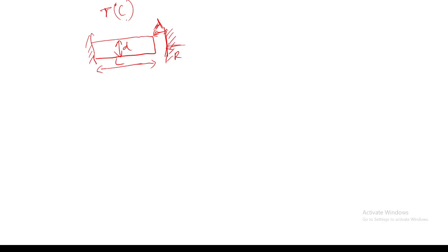Clear, sir. I am continuously increasing the temperature, and the thermal strain will be alpha T L. If this alpha T L is greater than lambda, then I will be getting a reaction force.